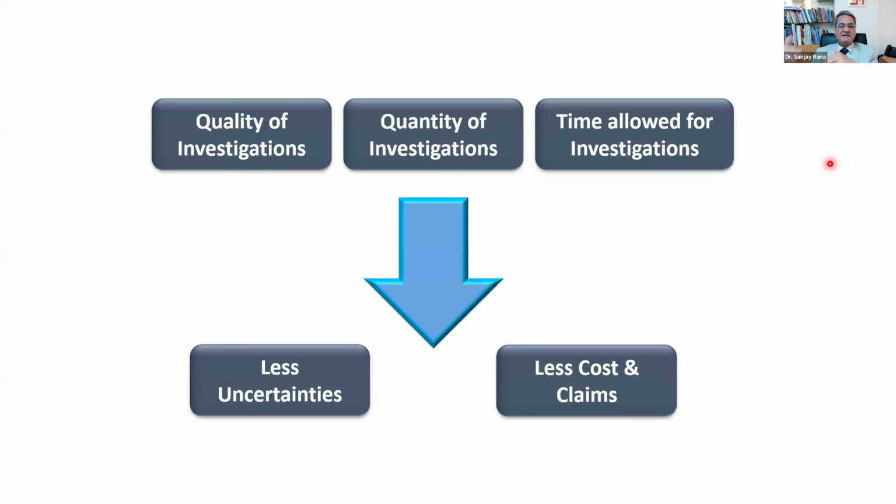And then we come across what we call geological surprises. That is, we were doing tunneling, suddenly we came across an aquifer zone. We were doing tunneling, there was a shear zone, etc. So the point is that expertise and engineering solutions are available for dealing with almost any ground condition. That is, if you know that you're going to come across a shear zone, you can pre-grout it and go ahead with your tunneling. Whatever the ground condition, there is an engineering solution to deal with that, provided you know about the expected presence of this particular zone. So the problem is meeting the unexpected and the uncertainty of the ground condition.